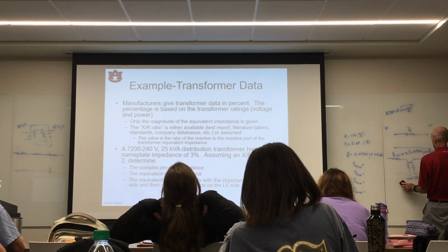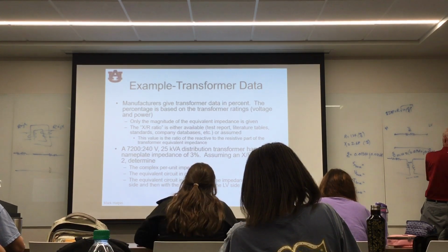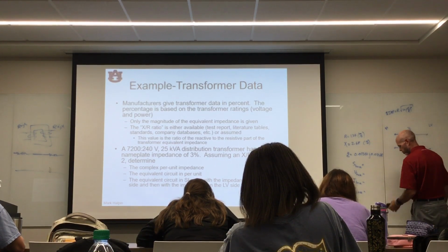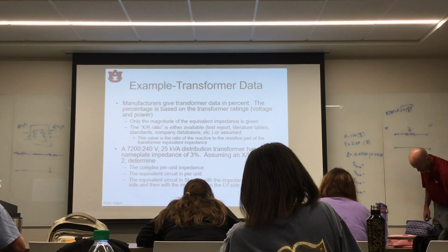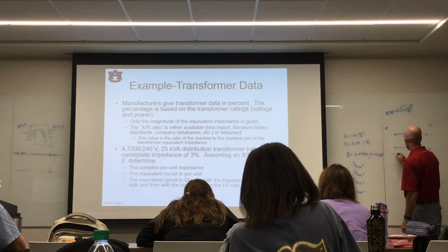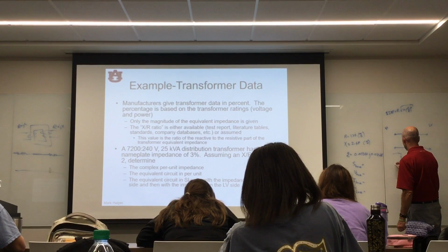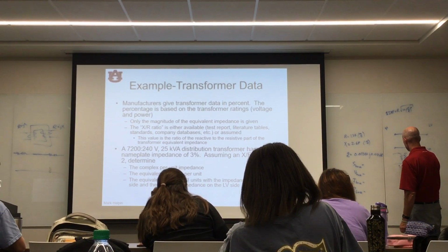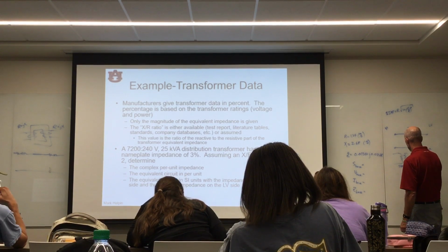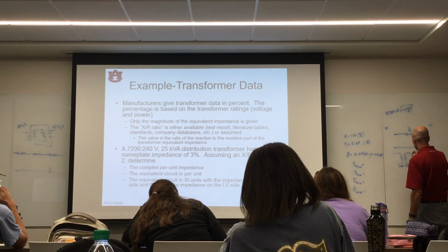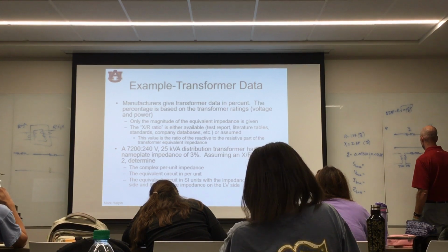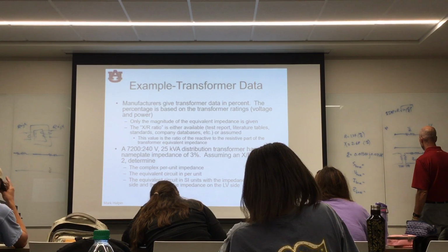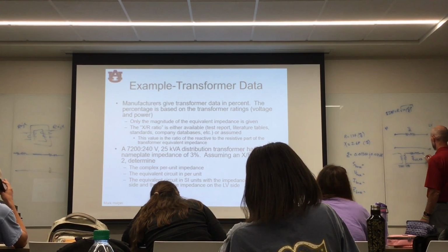Get rid of that, and get rid of all that. Now, let's do this again, except this time, let's put it on the low voltage side. So what does that mean? That means that the ideal transformer is here. The turns ratio or the rated voltages are still the same, but now the impedance I'm going to put there. And let's call this Z LV SI.